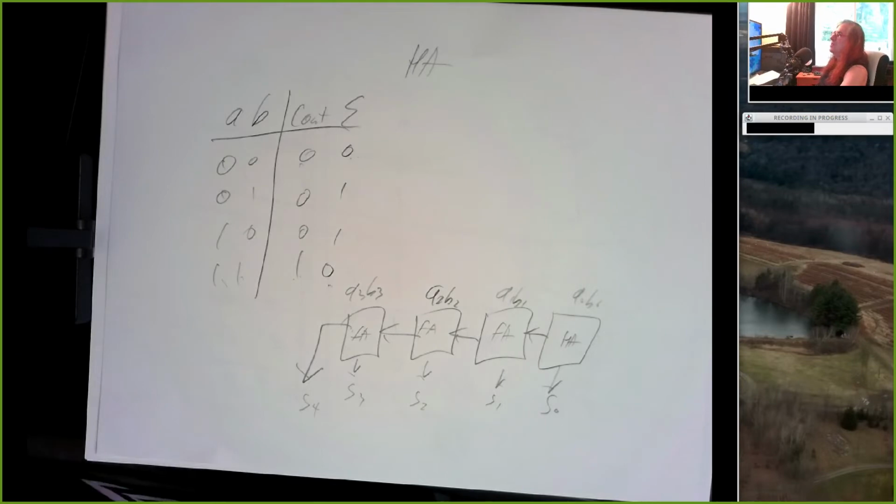So you'll be using ICs for AND gates, OR gates, NOTs, XORs, NANDs, NORs, those basic logic gates, and you're going to use those to create the half adder, full adder yourself. So don't use an add chip, implemented out of those fundamental gates.